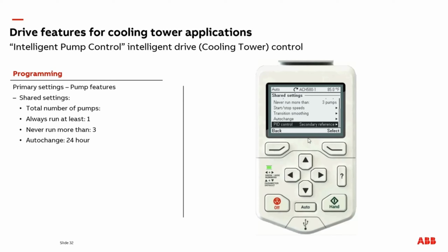And here, the default application is to use the PID control for the condenser water loop temperature. As demand in the loop increases and each fan gets above the starting frequency, another standby or follower fan will be brought on to meet the loop demand.